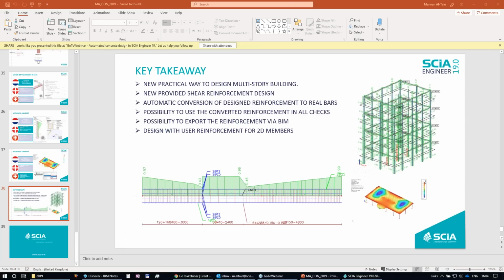Well, I have now three questions. The first one is about the anchorage. As I said, the anchorage is not calculated, but you can add it manually as a value. This value will not be controlled in SCIA Engineer. It's just from the visual point of view that we decided to add it. I'm working on it. I hope it will be fixed in the coming release, maybe not in 19.1, but my plan is to do it in 20.